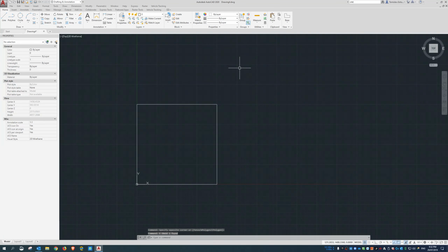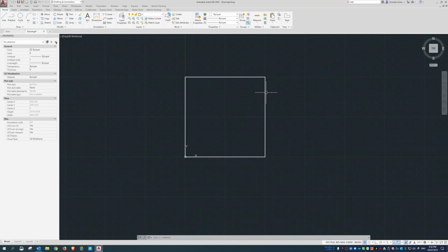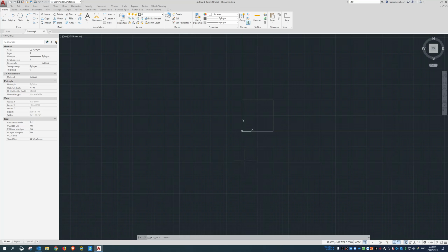And you can see that there are some grids in the background as well. So you can type in the word grid, and you can see it asks what the spacing is. I can do it at 10, or I can change it to 100, and you see the grids will change to 100 spacings. It's probably a bit hard to see on the video, but there are some very faint lines at 100 centers. So there are 10 of them. You can see there's 10 across in the X direction and 10 up in the Y. So that's where you get your majors and minors.